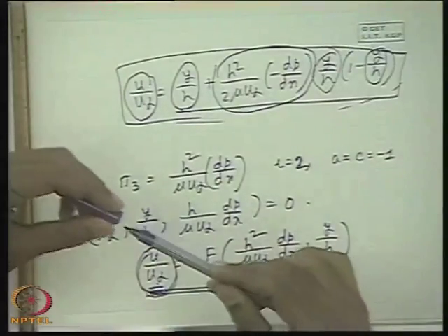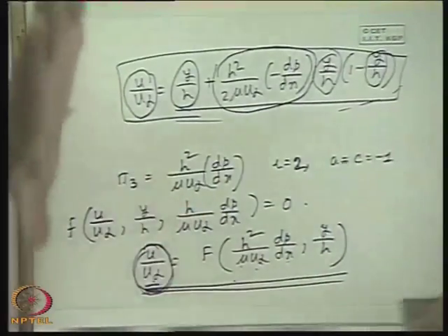What are the rules of Buckingham's Pi-Theorem? First, identify the problems by its physical variables governing the problem. That you will have to detect. Sometimes it is told, and in actual case it will not be told. For the purpose of examination it may be described. That is, a problem is described by these variables, physical variables. Then you have to find out, let m is the number of physical variables describing the problem. Then you identify the number of fundamental dimensions in which the physical variables can be expressed.